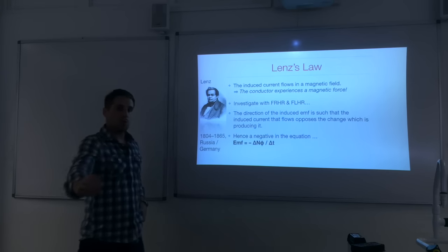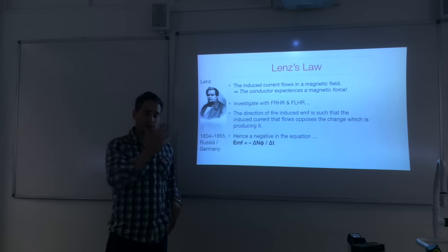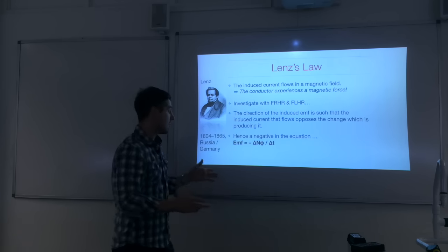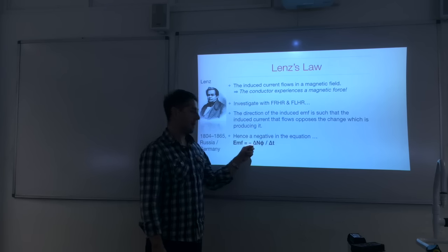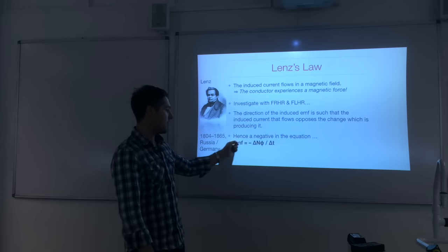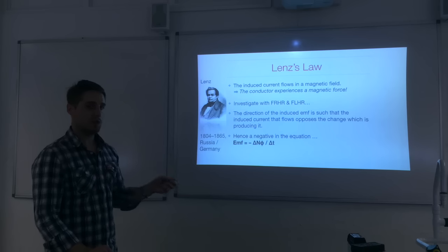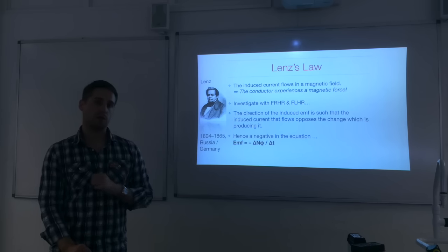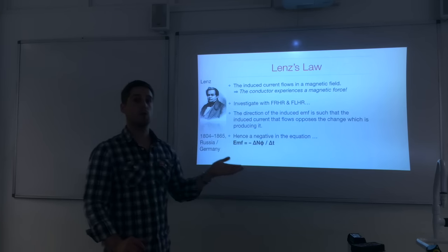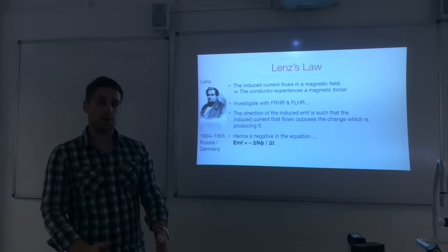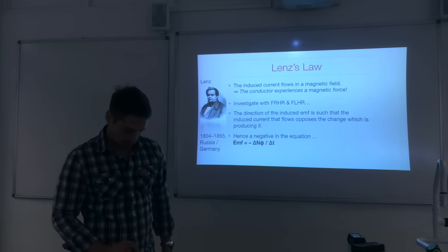So now let's take Faraday's law, and we can now say equals if we introduce this negative. So the induced EMF is equal to the negative rate of change of flux linkage. That's why there is a negative in the equation, because the induced EMF has got to oppose the change that caused it.